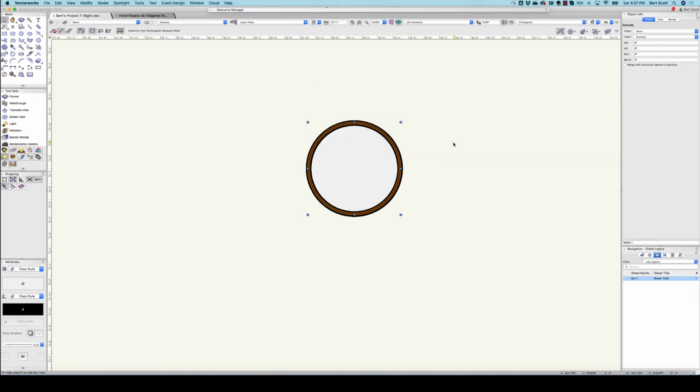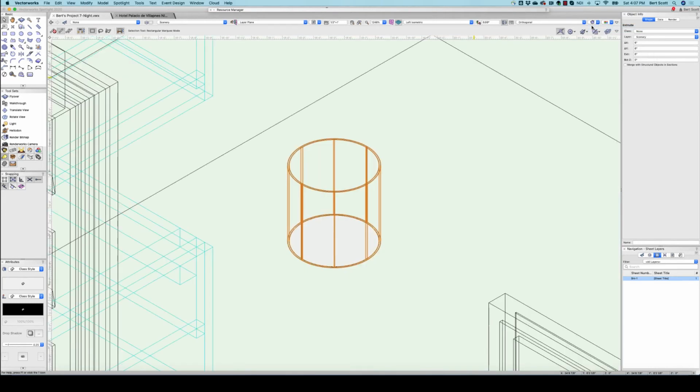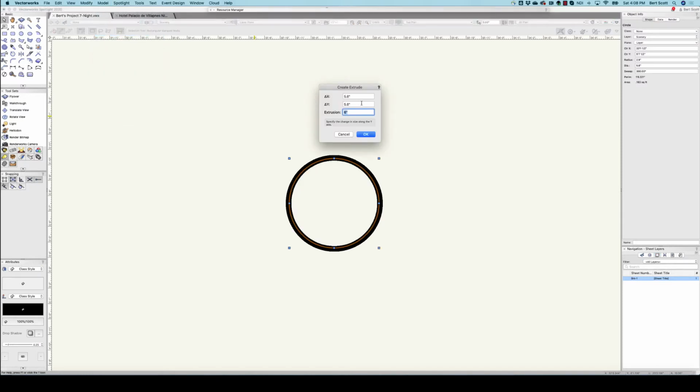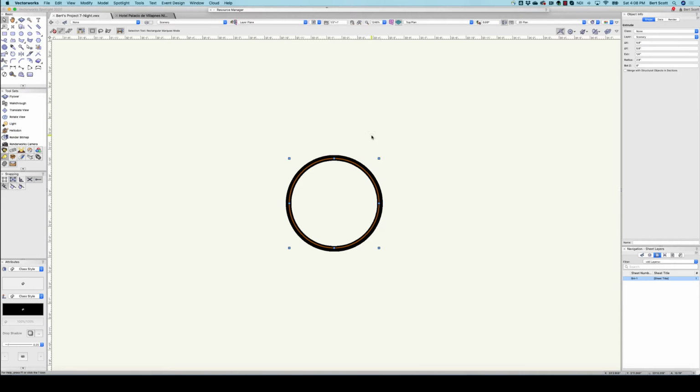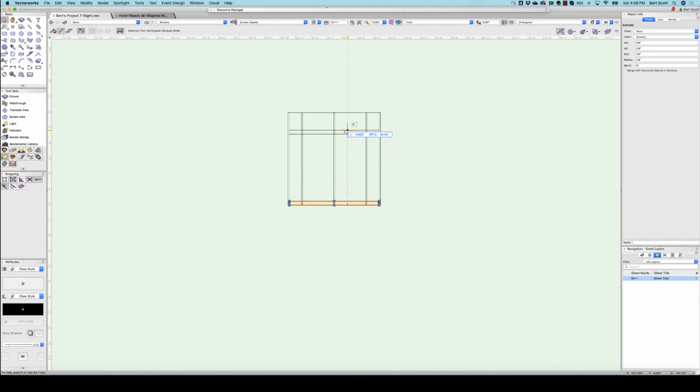And if I look at this in isometric, well, there's a whole room in the way, but that's what I have. Then while I'm there, I'm going to extrude this 1/4 of an inch. This is going to be the lens of my light. So I'm going to go to front here and wireframe, and I'm going to move this up so it's just about there, just below the top of the light.